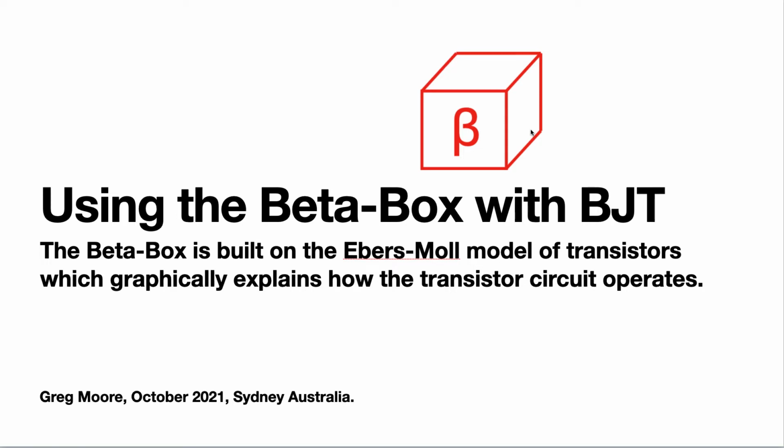This video introduces the beta box, which is a graphical method of working with BJTs in order to do calculations of voltages and currents. It's built on the Ebers-Moll model of transistors, which graphically explains how the transistor circuit operates. In the PowerPoint, I'll be showing Kirchhoff's equation versus the beta box, and you can see straight away after that that the beta box is very nice to work with.